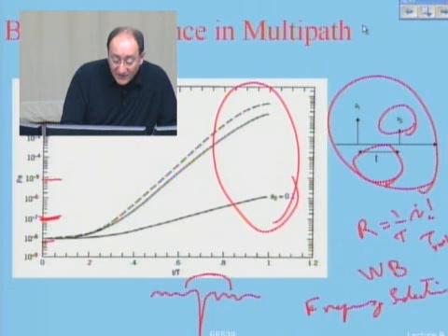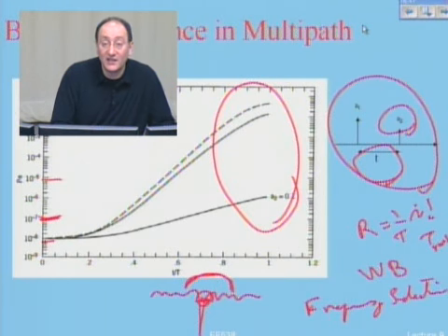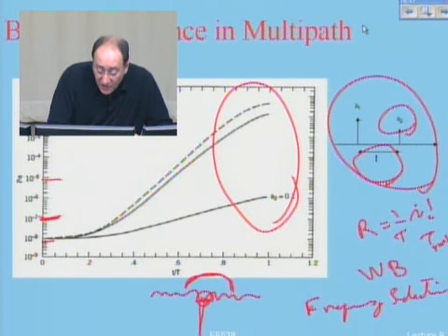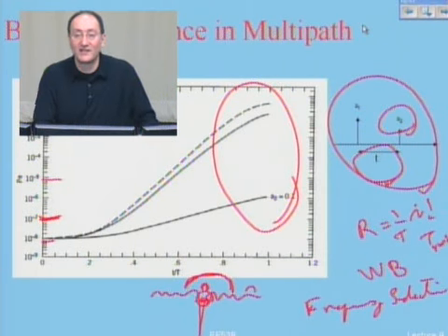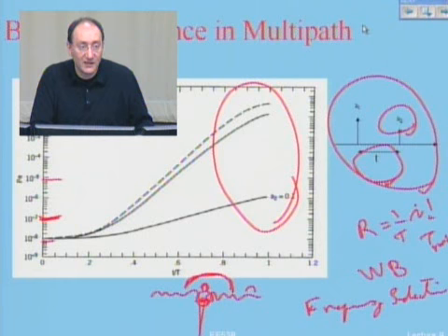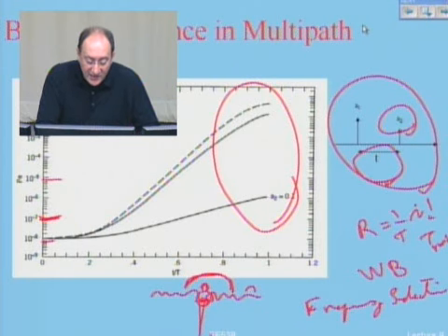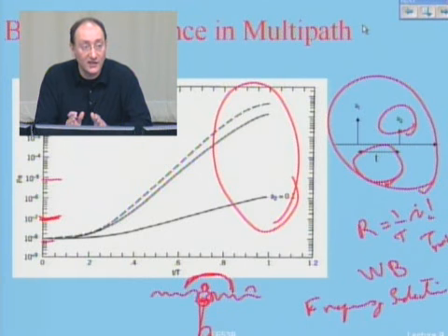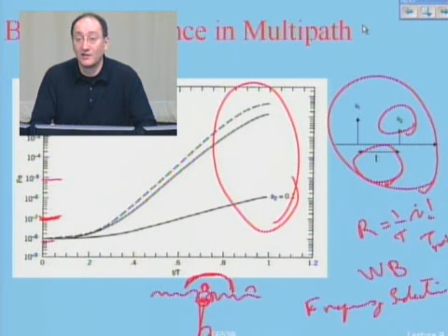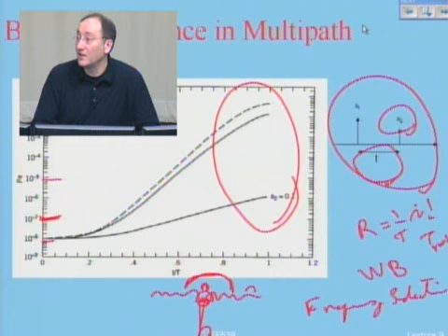This means that the bandwidth of my signal is comparable with the width of these things in frequency selective fading. In narrowband communication, I'm like this, very small band. You follow that? So either my channel hits the frequency selective fading or it doesn't. In wideband communication, part of my channel gets hit with the deep nulls or fading, frequency selective fading.